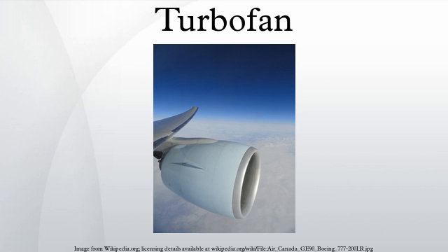Military turbofans. Most of the configurations discussed above are used in civilian turbofans, while modern military turbofans are usually basic 2-spool. High-pressure turbine. Most civil turbofans use a high-efficiency, 2-stage HP turbine to drive the HP compressor. The CFM56 uses an alternative approach, a single-stage, high-work unit.